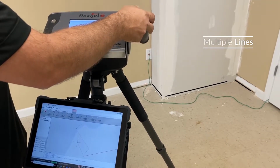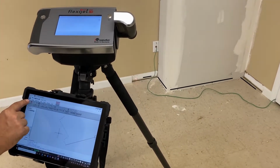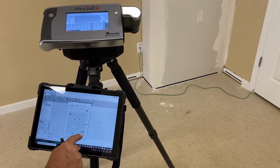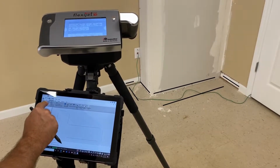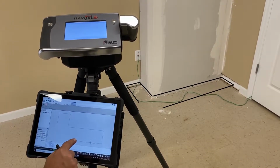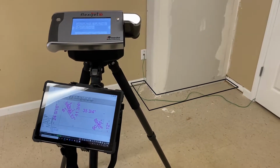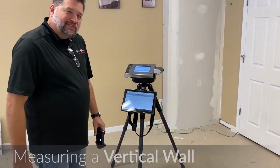And then we simply know that this customer wants that hearth to be offset 12 inches. That's a really nice feature. What we're going to do is basically align this to how it needs to be, and we'll go to offset, and we'll say 12 inches, sir. 12 inches and 12 inches. And then we'll connect those up for him. And then we'll hit auto dimension. And we can see we have all the information that you could ever possibly need. Great.